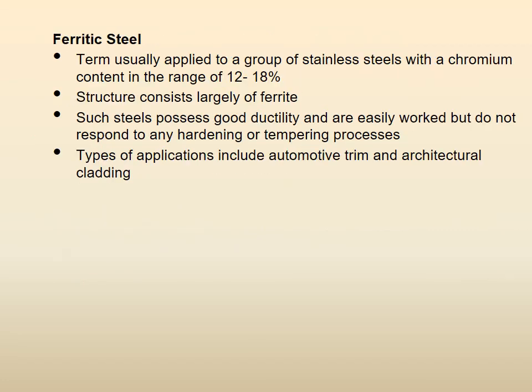So I have just added something which is not basically the fracture mechanism side, but what is ferritic steel, so that you are more clear. The term is usually applied to a group of stainless steels with a chromium content in the range of 12 to 18%. You know, chromium is added to steels to make them stainless, non-corrosive, and here a large amount of chromium, 12 to 18%. The structure consists largely of the ferrite phase. Such steels possess good ductility and are easily worked, but do not respond to any hardening or tempering process.